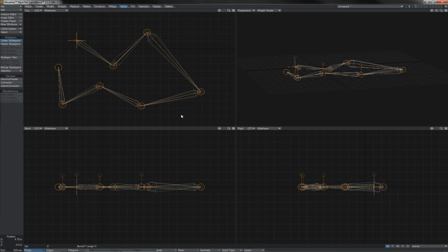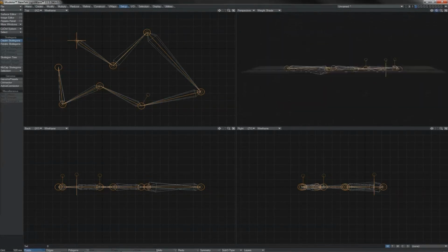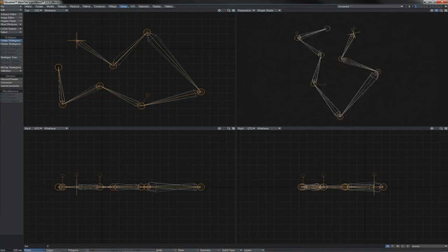And you could of course just draw your skeletons however you like in Modeler, bring them into layout, convert them, and then do all of the orientating of them. But you can do it here in Modeler itself simply by grabbing these little lollipops and nudging them about. I'll show you this. If I grab this guy here and I bring it down nice and flat like this, we can now see that whilst all of the other lollies are pointing up, that one is pointing across.